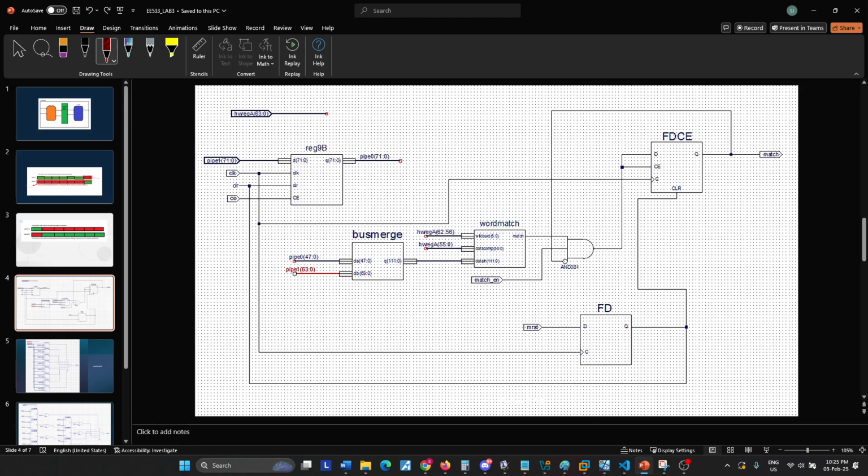Now, this data goes into a fall through FIFO, which then goes into the pattern matcher 7B module as you see on the screen. We need to consider the possibility that the malicious pattern is hidden, and that is exactly why we need this 14 bytes of data, as I explained before. One chunk has a few bytes of the matching pattern, and the next incoming chunk might have the rest of the pattern to be matched.